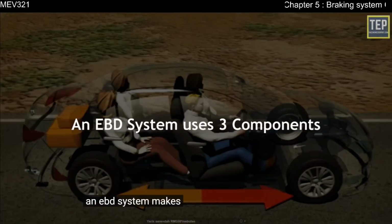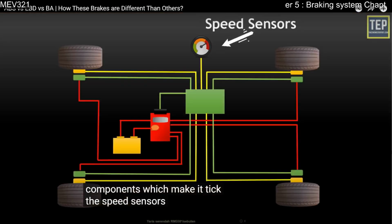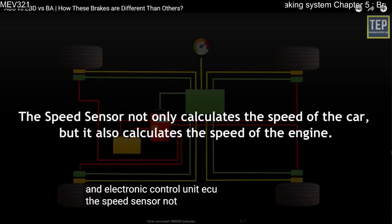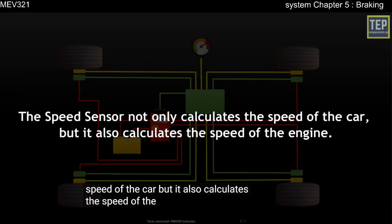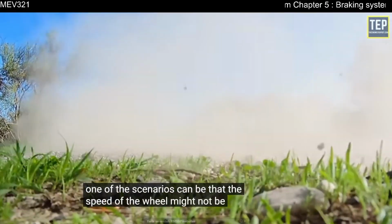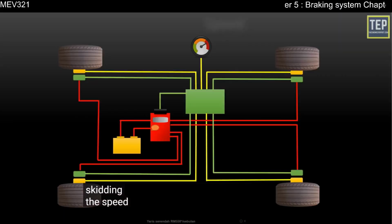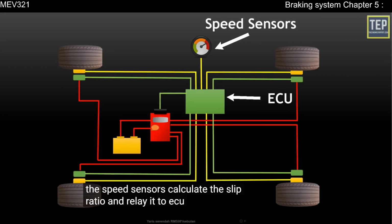An EBD system makes use of three components which make it tick: the speed sensors, brake force modulators, and electronic control unit, ECU. The speed sensor not only calculates the speed of the car, but it also calculates the speed of the engine. One of the scenarios can be that the speed of the wheel might not be the same as the speed of the car. Such a situation can lead to the wheel skidding. The speed sensors calculate the slip ratio and relay it to the ECU.